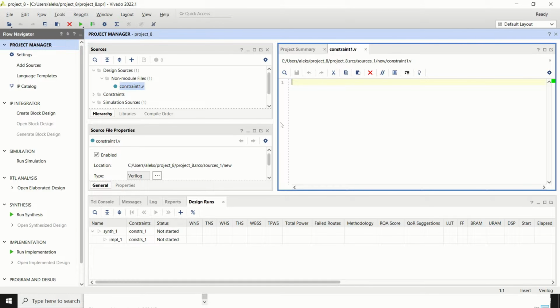And over here we need to define our logics. Basically, we need to define a module. So what is a module? A module is basically a function that takes inputs and outputs and defines your logics. So let us write module circuit 1, and here we need to end the statement with a semicolon, and we need to end the module. So this is our module. Here we need to specify inputs and outputs.